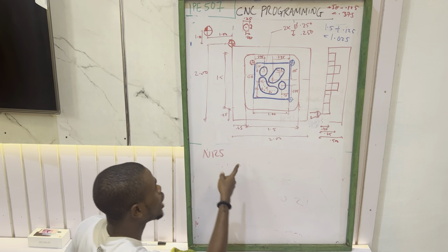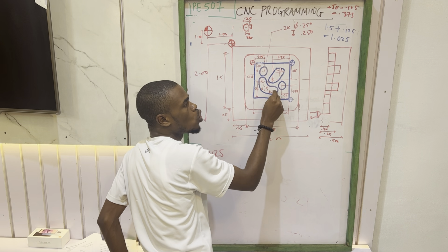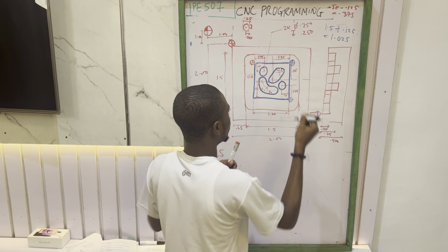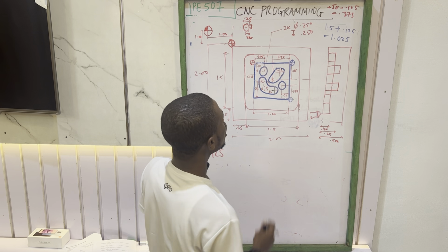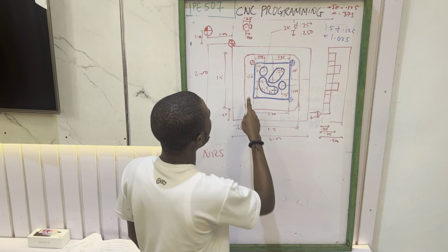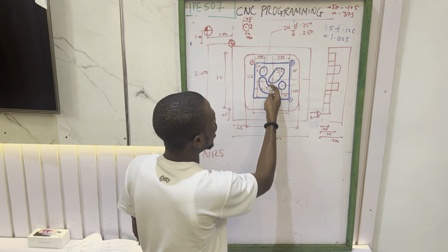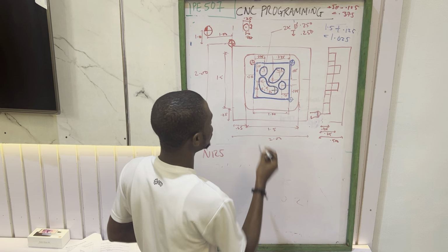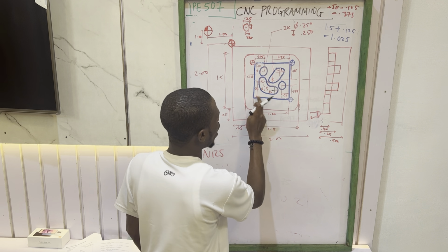So the next operation is N125. So I've successfully drilled this place. So I now want to move it from this place to this place, where I have my black marker. So I have to locate the point of this place. Locating the point of this place, let's locate it together and see. On this part of the X, this is 0.25, 0.25. And I think these are the center. I think these fours are the center. So this place is 1.25, and here is 0.5.